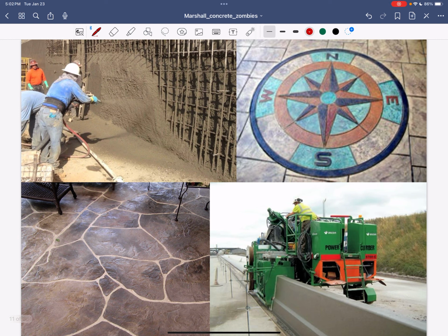A couple other ones here. Similar to the bidwell, this guy here is making a median, right? And so this concrete is so thick that it actually just drives in this direction, and the concrete is formed without having any exterior form work on it. And you guys are welcome to ask me questions next week when I'm in class. So I'm going to go fairly quickly now with this.